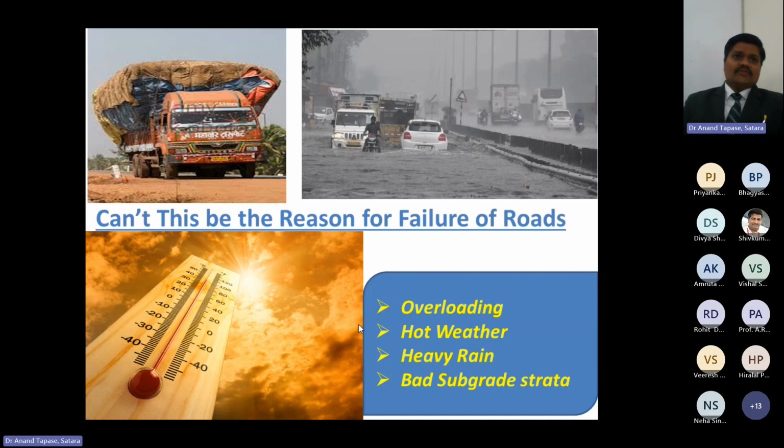Considering the example of softening point, the average climate from the Indian perspective in a region like Rajasthan is around 45 degrees Celsius. In the Maharashtra region, we can say the maximum temperature is 42 degrees Celsius. So whenever we are using bitumen or tar in road construction, we should have the softening point above the average maximum temperature. That is one of the things.